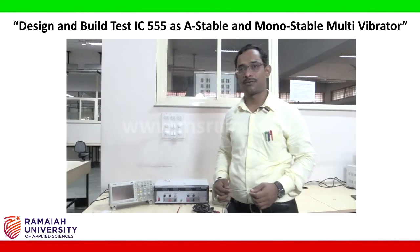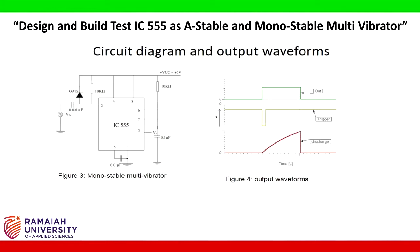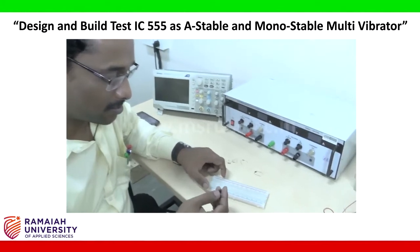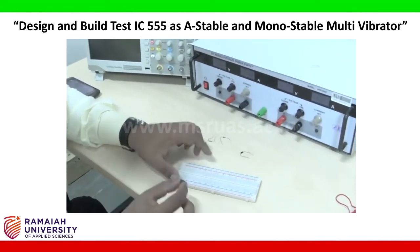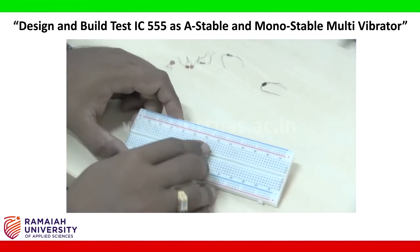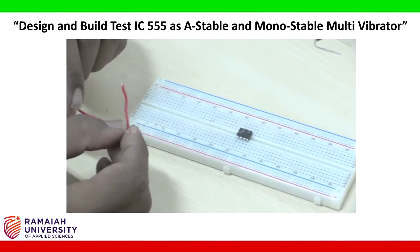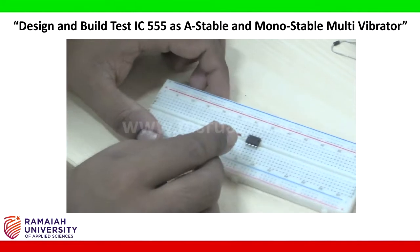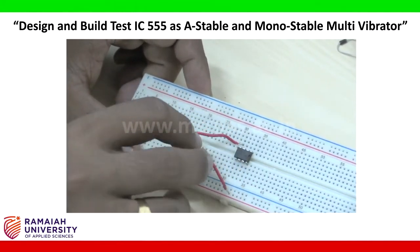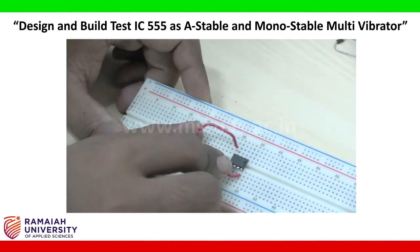Now let us start the circuit connection of the monostable multivibrator based on the circuit diagram. I am taking the circuit board and the IC 555 timer. I place the IC 555 timer on the circuit board. You can place it anywhere on the circuit board, there is no problem. Next I need to short pin number 4 and 8. This is 1, 2, 3, 4, the fourth pin. I am going to short it with the 8th pin. Now this is shorted.